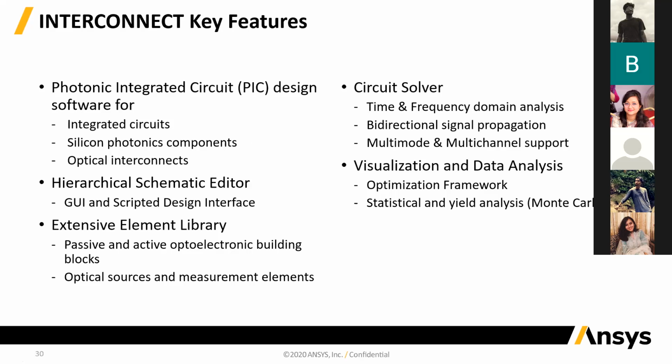You have building blocks for your circuit, and you can have multiple layers of circuits. That's why it's a hierarchical solver. It has an extensive element library that comes with different compact models for passive and active optical components, and different sources and analyzers, so that you can set up your circuit, hook it up with different sources and look at the results.